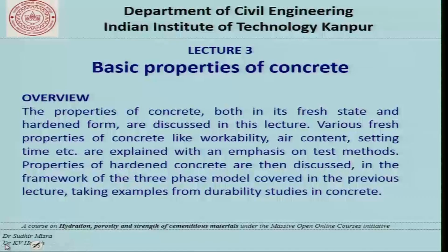Various fresh properties of concrete like workability, air content, setting time are explained with an emphasis on the testing methods, and properties of hardened concrete are then discussed in the framework of the three-phase model that we talked about in the last class, and we take examples from durability studies in concrete.